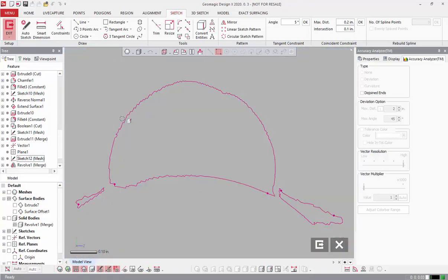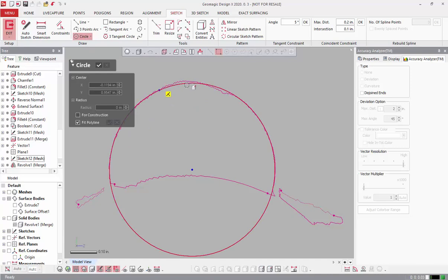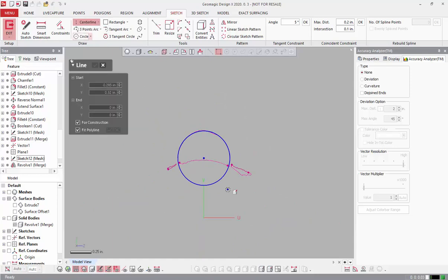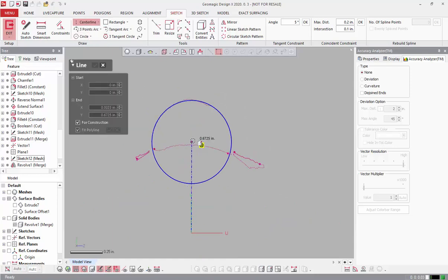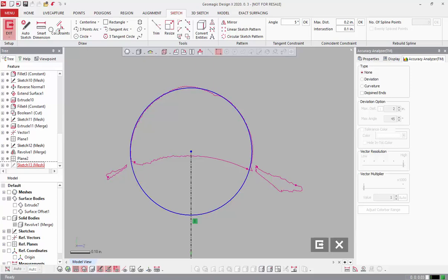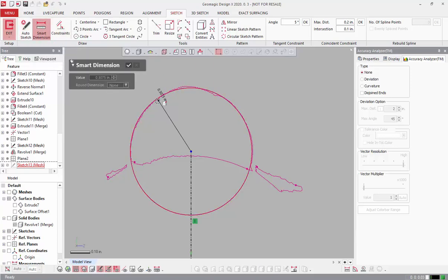sketch mode, not the cleanest cross section, but let's see what happens when I fit a circle to it. It's going to be a couple high and low areas, and that's to be assumed. If I want to try and do some full definition for this sketch, I can of course create a construction line to the origin, make it vertical so that it's directly on the center line or the plane or whatever it is there. And then of course, once I best fit a value,